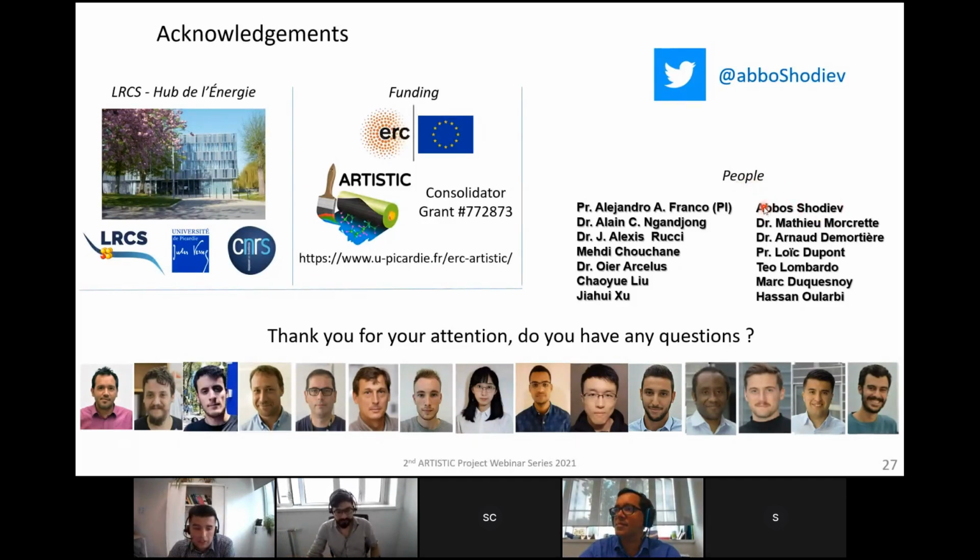Thank you very much, Alexis, for this question. It's a very important question because we know in the electrolyte infiltration step, first we apply vacuum, and then inside the vacuum, the electrolyte goes in. In the model I presented, gas is inside already, then it goes out due to the applied force, and then the electrolyte takes its place, right? But this simulation can easily be divided into two steps.